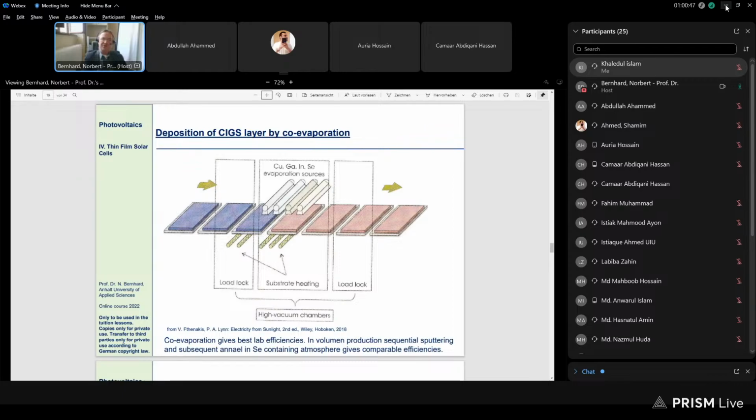You see the first publication by Michael Grätzel was in 1991 in Nature. And there he published 7 to 8% for this cell. And what we see, we have a glass substrate, again a TCO, a very thin platinum electrode, and then we have an electrolyte. You see this in principle is a liquid solar cell.